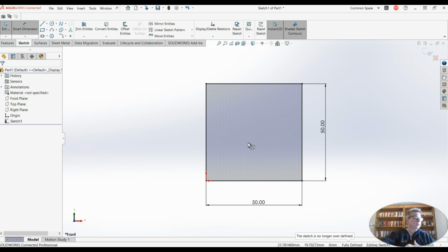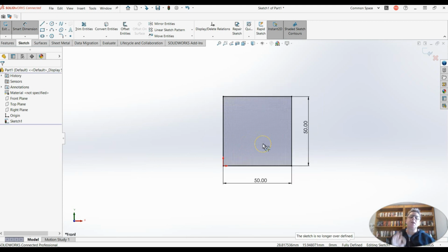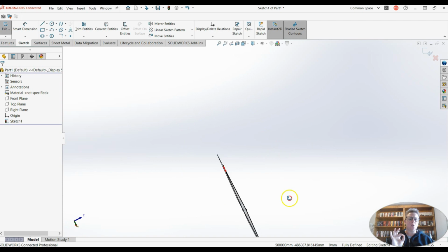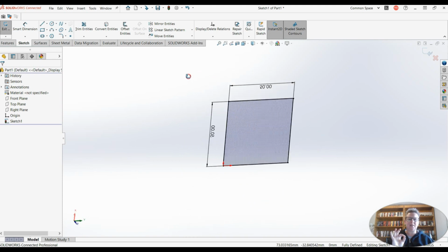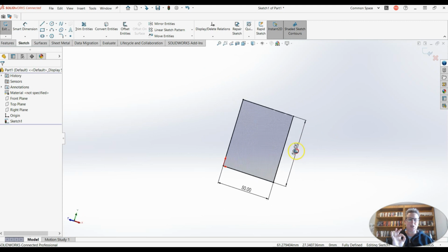Now here's a little magical tool with our scroll wheel. We did our scrolling in and out, in and out, in and out. If you treat your scroll wheel like a button, in other words, if you use whatever finger is comfortable to press and hold, if you actually press that scroll wheel down like it's a button and hold it down, and then move your mouse, this is called orbiting. All right, so that's pretty cool. That comes in really, really handy in time to come.